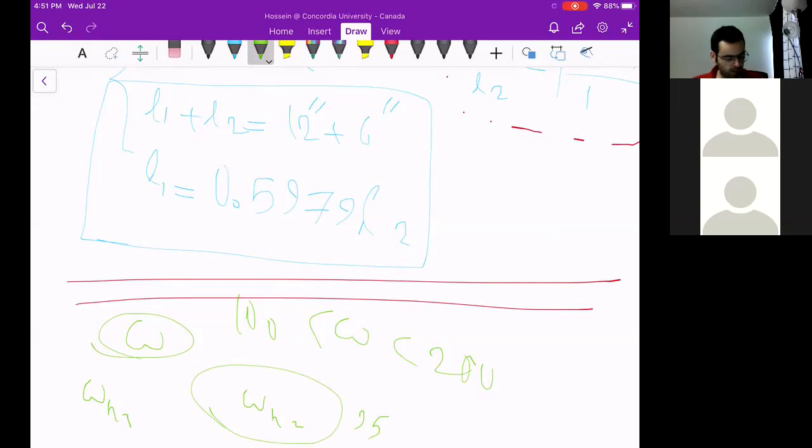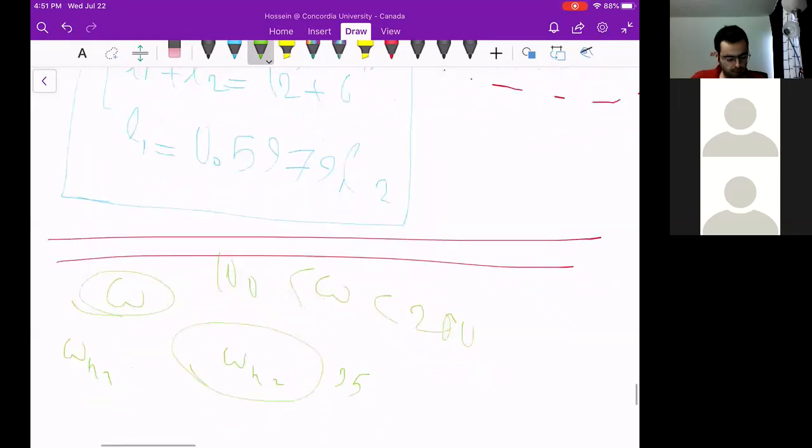So you have to change the stiffness to make it lower, like 35, to be far away from the excitation frequency in order to reduce the vibration. And the node just gives us how this system will behave.